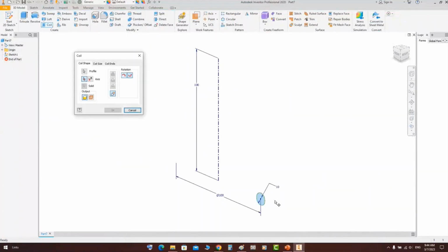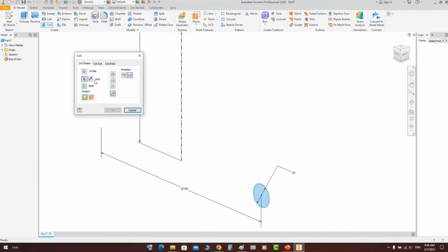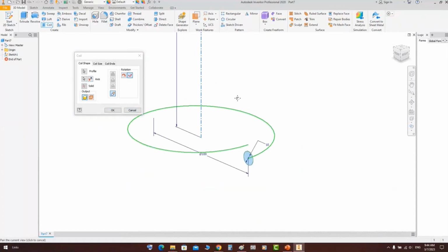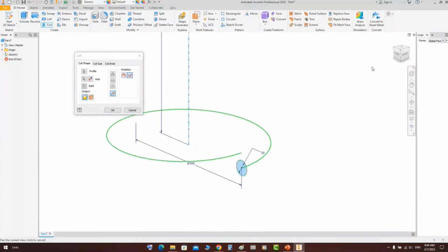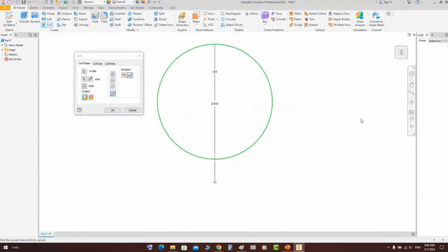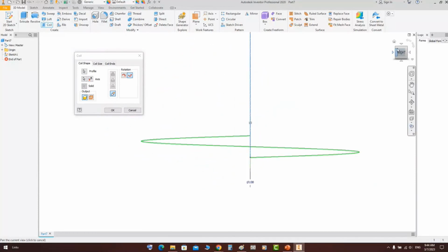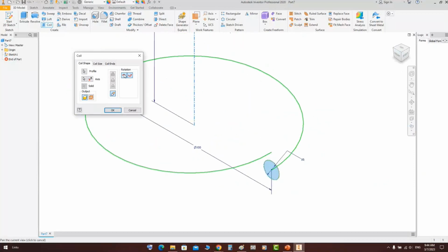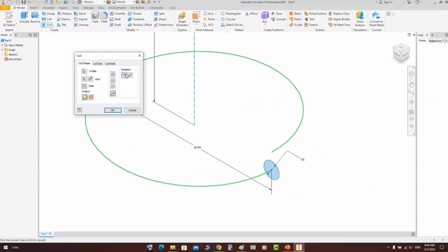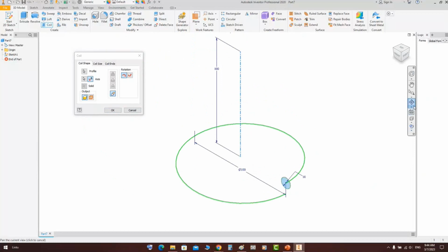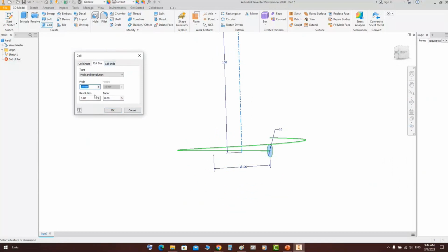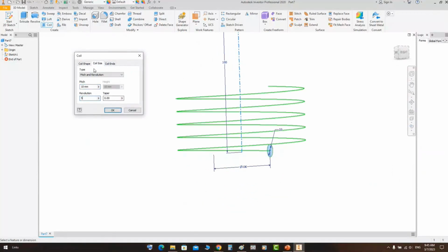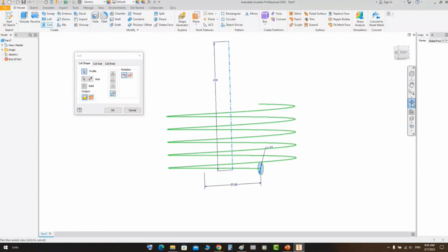Now if you select coil, automatically the closed area will be selected. Now you will need to select the center line of the coil. When you select this center line, you will be able to, if you take a look from, let's say that view, from the 3D view, you can flip the orientation. You can make it clockwise or counterclockwise like that. Okay, and flip the X direction, make it on the top or bottom. So you can figure that the coil will go to top like that. If we increase the number of revolutions, let's make them 5 right now. After that, we will discuss those options in detail.